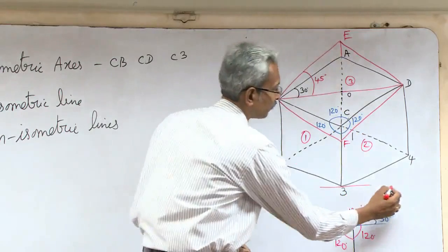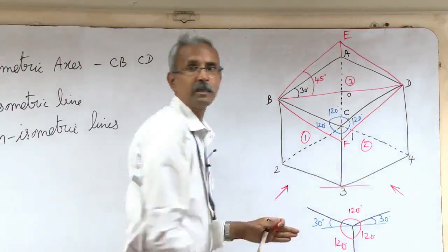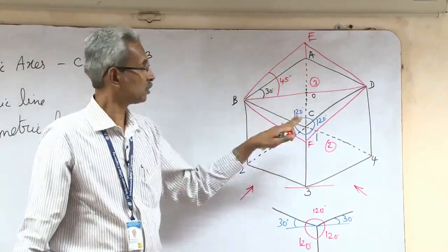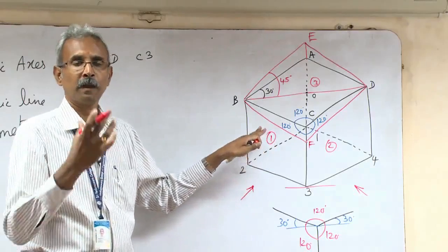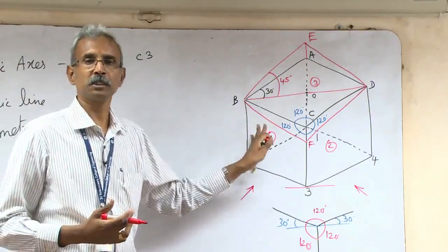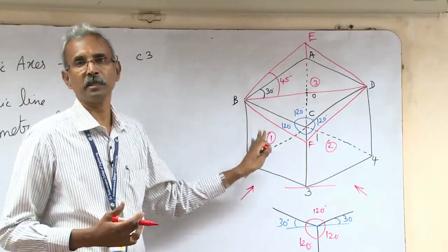And similarly, if I am going to view from this direction, then this will be my isoplane front, isoplane left and isoplane top. This is important because later on you are going to have a topic wherein you will convert isometric drawing into orthographic drawing, wherein you have to use this concept of isometric planes, isoplanes.